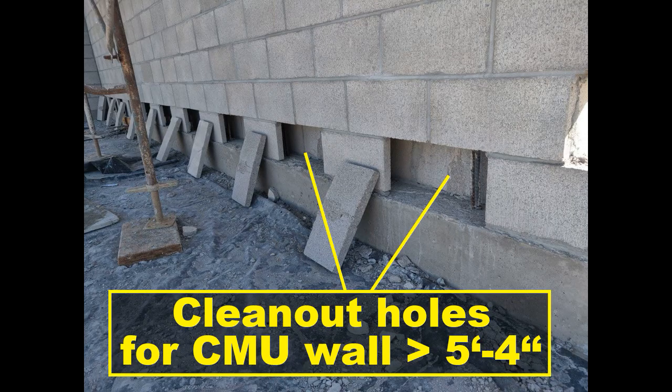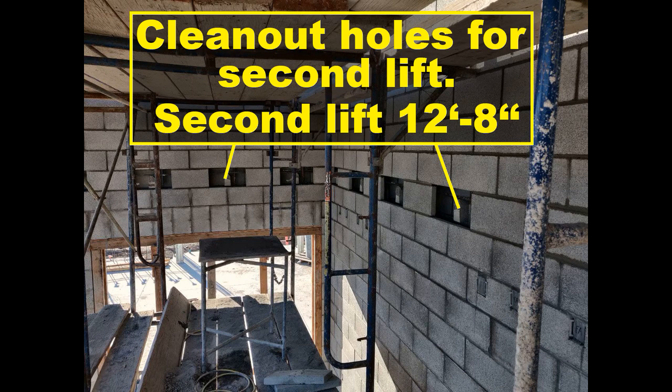Cleanouts for hollow unit masonry construction. Provide cleanout holes at the bottom of every grout pour in cores containing vertical reinforcement when the height of the grout pour exceeds 5 feet 4 inches. Where all cells are to be grouted, construct cleanout courses using bond beam units in an inverted position to permit cleaning of all cells.